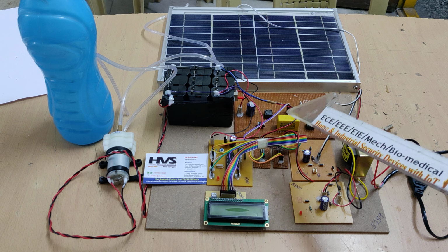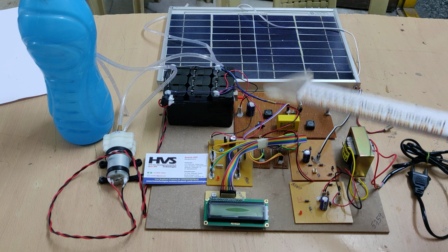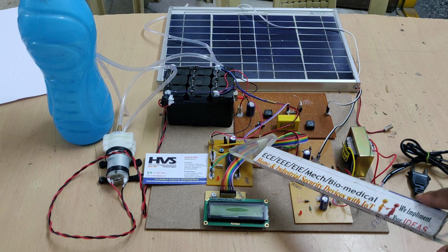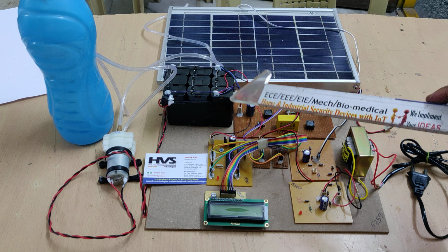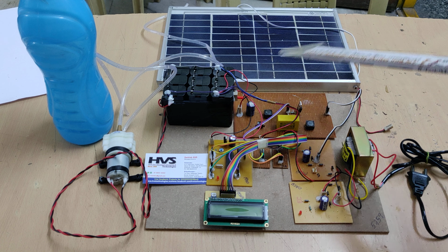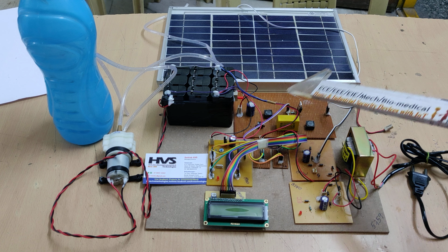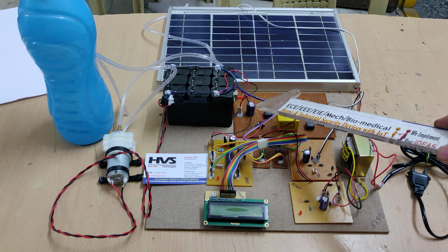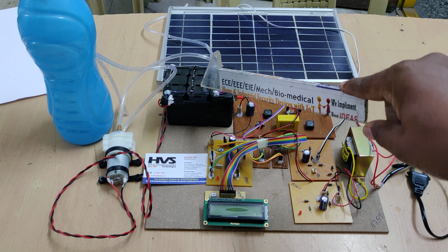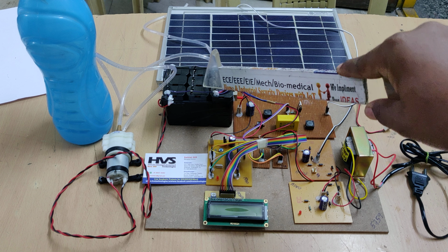So at some point of time, maximum voltage and maximum current are reached. That point is called the maximum power point, and that will be tracked with the help of our PIC16F72 microcontroller. Coming to the application, the solar panel successfully generated the voltage, our microcontroller measured that and controlled the voltage, the maximum power point was reached, and the battery got charged with the maximum power, so the charging time will also be decreased.